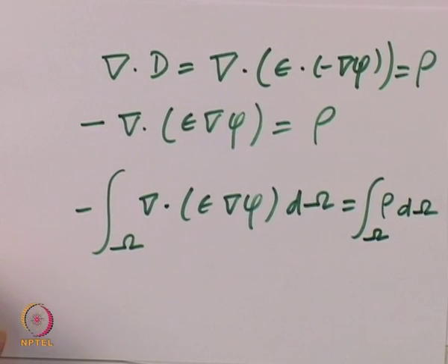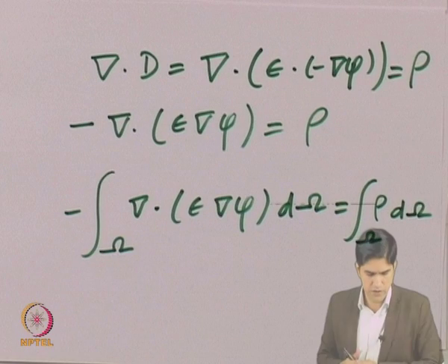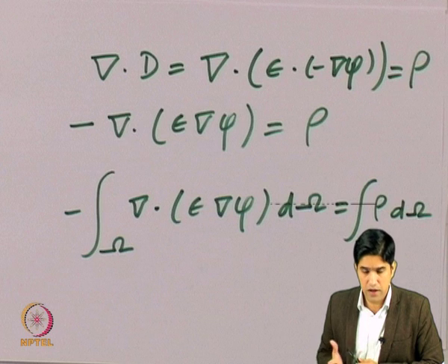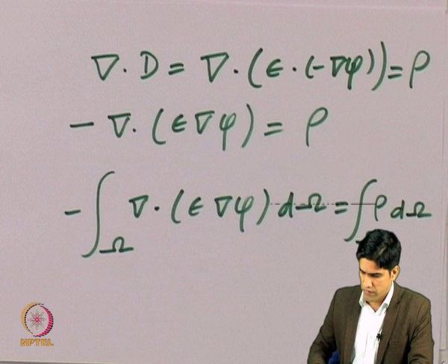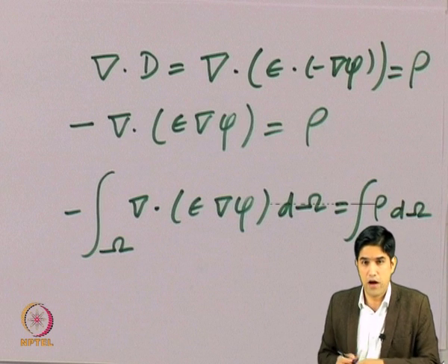I said we can do finite element in two ways. We are going to use the weighted residual method and we can also use the Galerkin approach. The Galerkin approach and the weighted residual method only differ by the weighting function, which in Galerkin is made equal to the basis function. Let us take a simple starting point where we start with the weighted residual and then decide how to go forward.